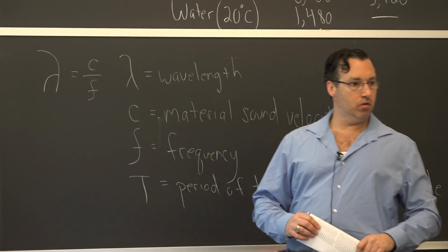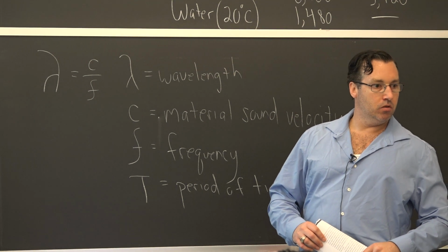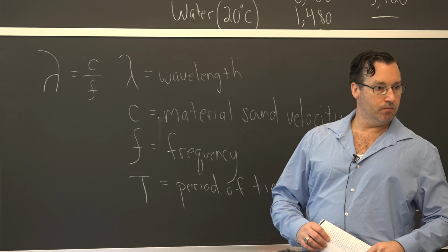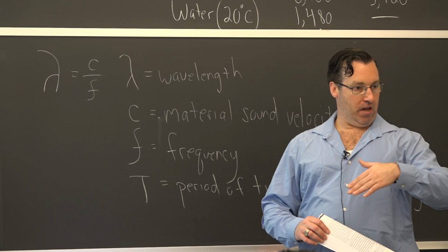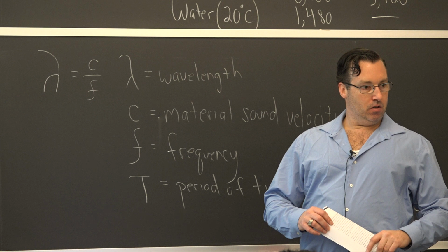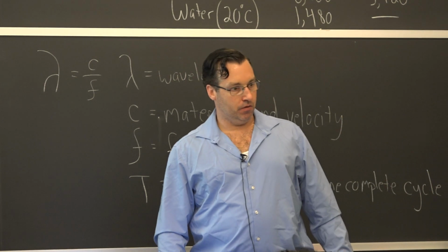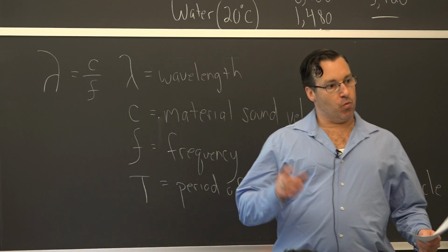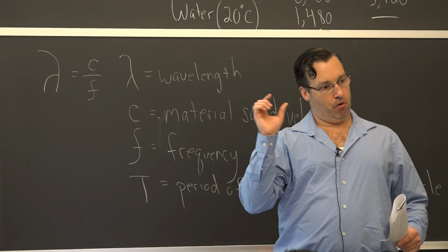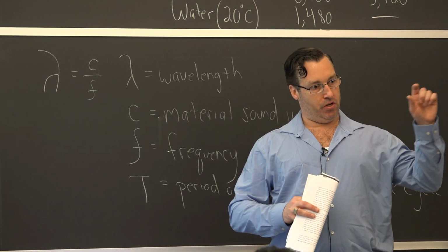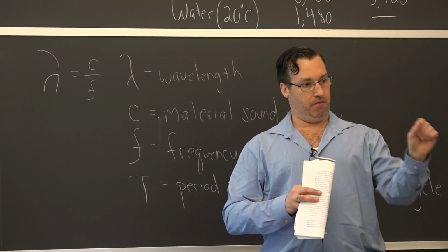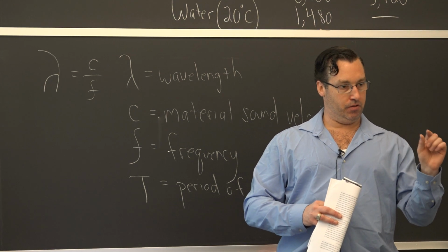So if you're measuring a few megahertz, and your wave speed through most materials is a few thousand meters per second, that puts you at about a millimeter for the wavelength. How are you going to see defects that are much smaller than the wavelength? That's when you tie in shear waves. Shear waves are a little bit slower, but only by a factor of 2 or 3. So if you want to see a 10 thou crack, that's a quarter millimeter, which could be significantly below your wavelength. And that's where it ties into the confidence level. So rather than a 95 POD 90 CL for confidence level, your confidence level may only be 80% if you're trying to find something that's only mils in flaw size.